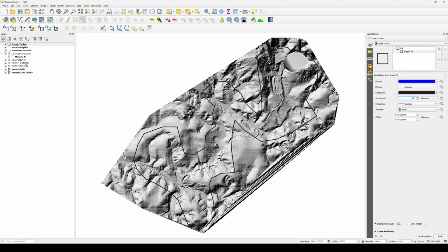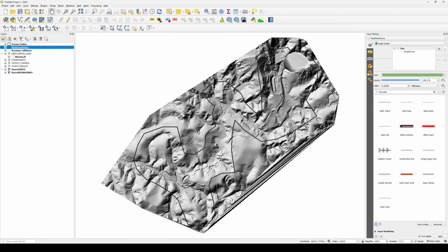The next thing I'm going to do is create a mesh density line. I'm going to click on this layer. And the reason why is to give the channel in the middle more triangles. We're going to densify it a bit to give us a little more detail where the spill is going to occur. So I'm going to go ahead and edit and then click on the add line feature button. I'm going to start from the beginning here of the raster for the tailings.